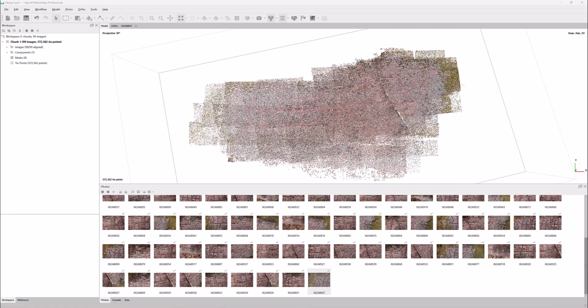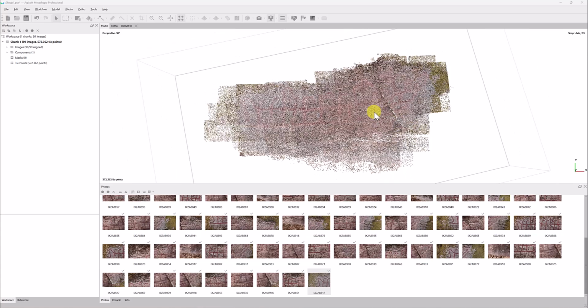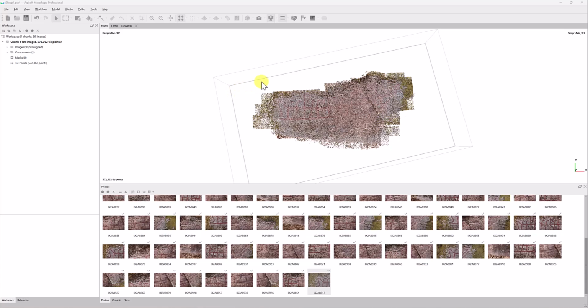The next step is to use the sparse point cloud to create a denser mesh that can be used for creating DEMs and 3D meshes. By the end of this stage, your model should be quite recognisable as the object you photographed. In recent updates, Agisoft have moved more towards skipping the dense cloud creation, though it's still highly useful as a step for cleaning up meshes and testing quality before a model is built in certain workflows.